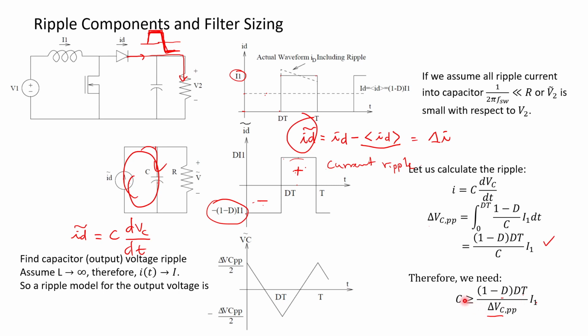Maybe you wonder why you got the sign bigger. Anyway, the bigger the better. Also, in terms of real design process, when you calculate C and you look at the commercial capacitor, maybe you cannot have one that has the same specification as your calculation, right? It should be different, and you need to choose the bigger one, not the smaller one.